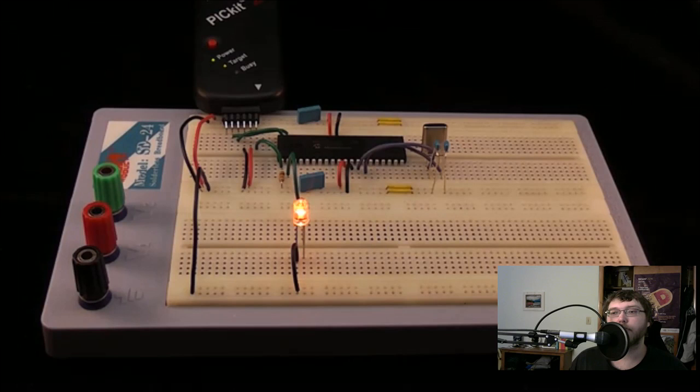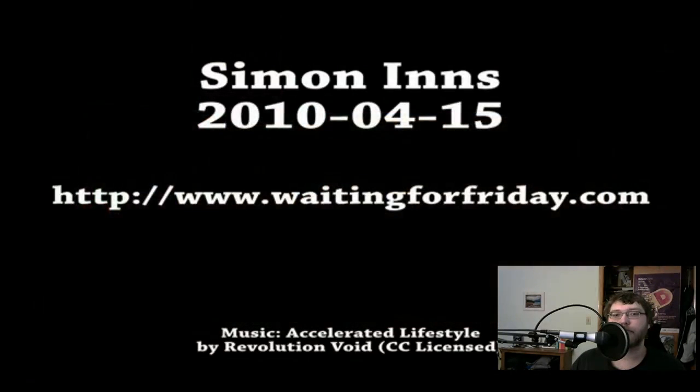Whilst it's perfectly possible to get PWM controls to work with LEDs using pure guesswork, calculating the desired optimum values makes more efficient use of the available processor resources, allowing you to both do more with the microcontroller and also control more LEDs simultaneously from the same chip. The same technique shown here for LEDs can also be used to control motors, analog meter displays, incandescent light bulbs, etc. You can find out more details about this guide and some example PIC18F4550 firmware on my website.